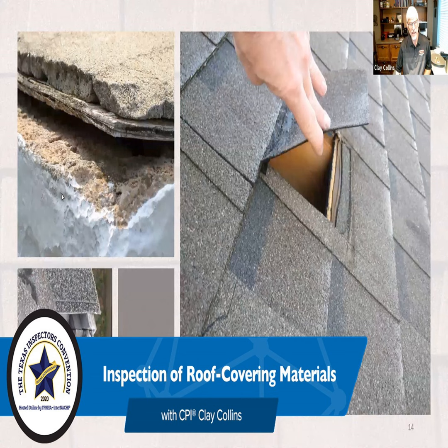All of these you can see, and all of these I would report as deficient because remember that one nail hole I showed you before? That one nail hole over 13 years caused some pretty major damage. But let's say that you have some problems with that. It's an easy solution. You just nail it from the attic space. Just come right on up there. That'll certainly hold it in place.